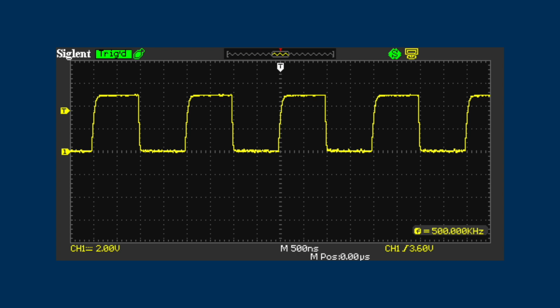All right, and finally, the LIC, or last instruction cycle signal. The 6809E raises this signal on the last cycle of every instruction. Since we have a 1 megahertz CPU clock, and each 6809 instruction takes a minimum of 2 cycles, we would expect an endless stream of NOPs to run the LIC at about 500 kilohertz, and that is in fact exactly what we see. So it looks to me like the CPU is in fact running an endless stream of NOPs.